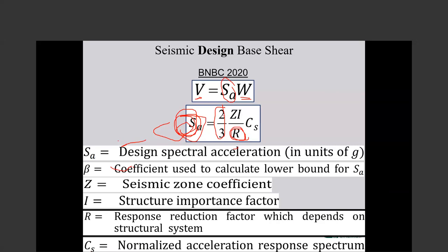We had it previously in things such as the P delta effect, for example. The P delta effect is a nonlinear, second order analysis too. But we wanted to design a building for P delta using elastic linear software.